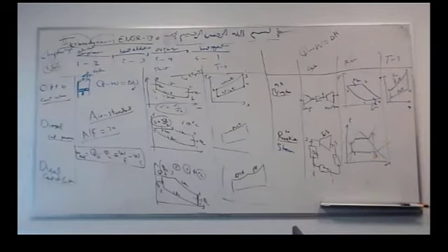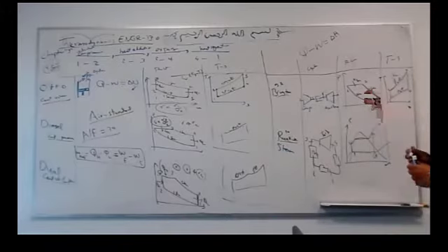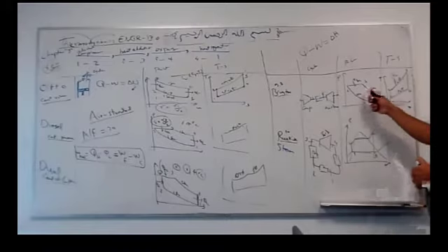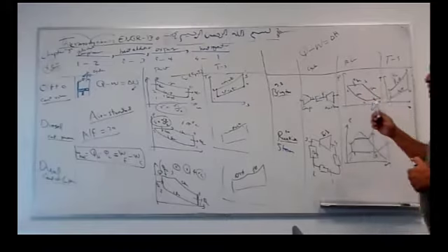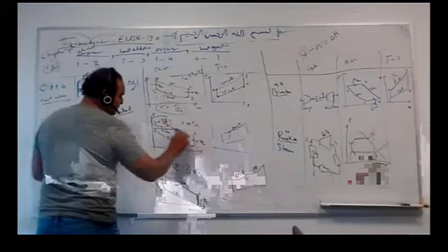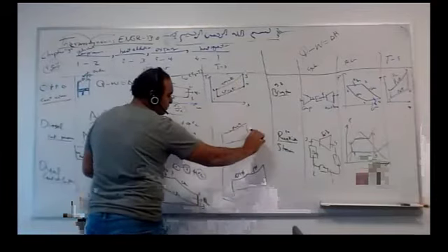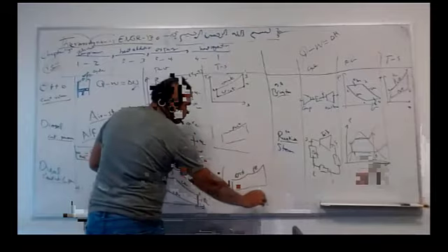Okay, guys? Always don't forget to write on the non-vertical and non-horizontal lines, isentropic or pressure constant. Here I don't need to write vertical lines or horizontals. But this one I need to write isentropic. Volume constant, pressure constant, volume constant, pressure constant, volume constant. Here, isentropic, isentropic, pressure constant, the same as here.